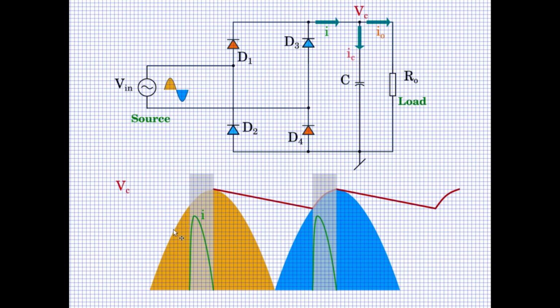As the capacitor is building up the charge, there is current flow to the rectifier, and therefore the rectifier current will be for this whole half cycle. So you will see the conduction period will start increasing, and it will be for the complete half cycle. Likewise, the current waveshape also will get modified something like this.